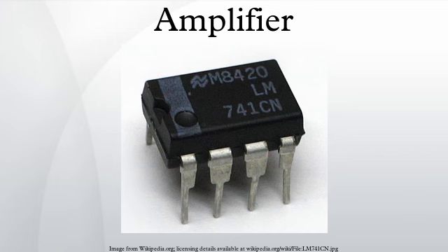Sometimes a numeral is added for vacuum tube stages. If the grid voltage is always negative with respect to the cathode, the class is AB1. If the grid is allowed to go slightly positive on signal peaks, the class is AB2.